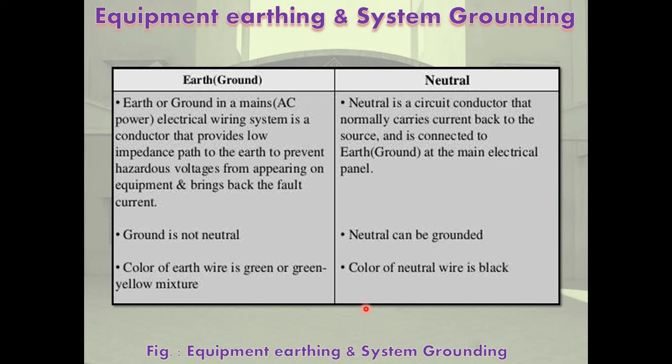The measurements of wattmeter and energy meter are not stable without neutral earthing of the secondary stars of three-phase CT and VT connections. Neutral earthing provides a return point for earth fault return current and provides facility for simple earth fault protection.